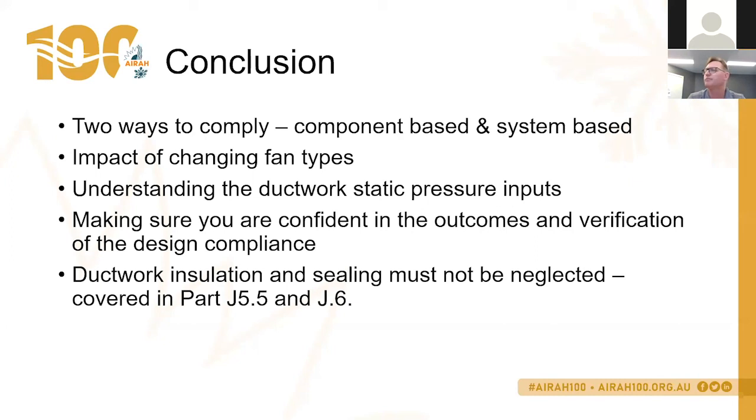The Building Codes Board, in your proposed system, you will potentially have a much higher flexible duct pressure loss, but the Building Codes Board decided that they would do the assessment based on flexible duct being straight and well installed, and not make any allowances for additional pressure losses. So they considered it a method to, I don't know, drive better installation practice.